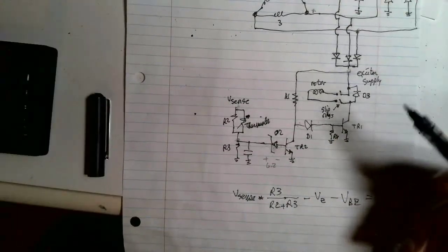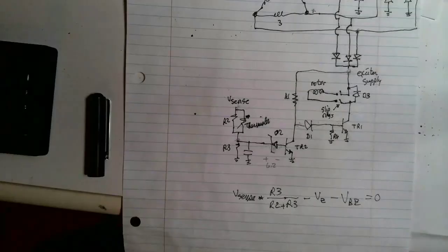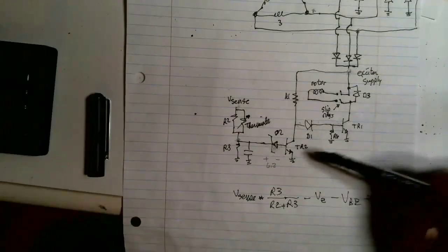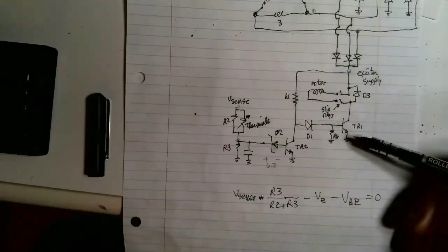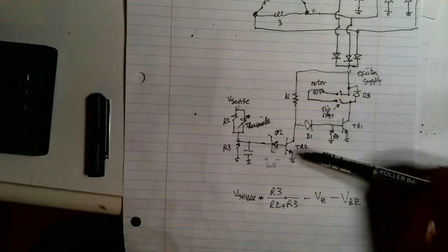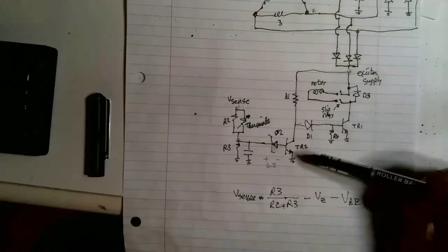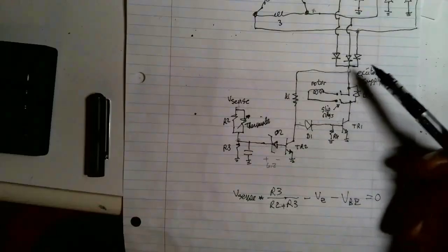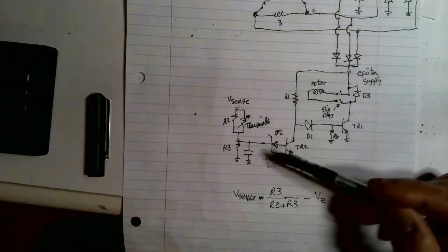So that is how I'd like to talk about the gain of this a little bit, but this video is already way too long, so I'm not going to talk about the gain of it. But it's very beta dependent. You notice there's not a whole lot of resistors here that set gains, so it's temperature sensitive and device sensitive from a gain perspective, and it's not the best design in that regard.